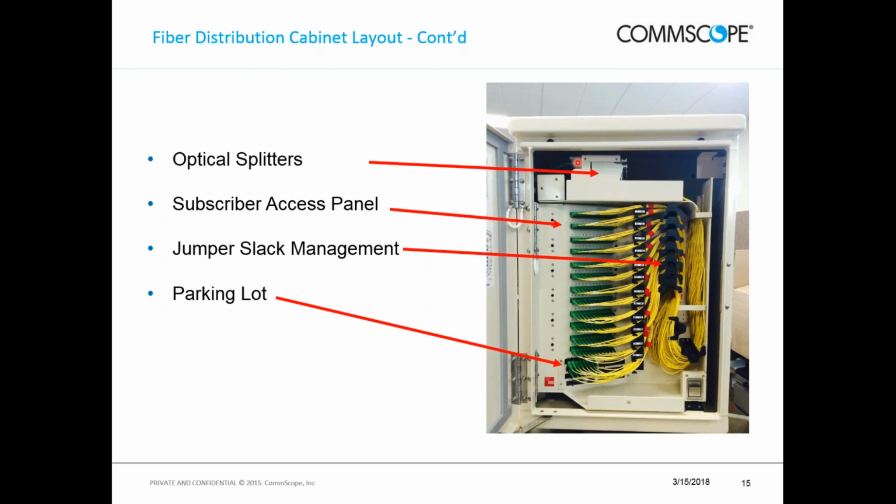So that's the feeding fiber of the splitter. Then this device where you can't see it, but there's 32 2-meter pigtails that route out down, and then up through the cable management and into the subscriber access panel. At this SC angled bulkhead panel, every one of those ports on the bulkhead panel is basically connected directly to a customer out in the field.